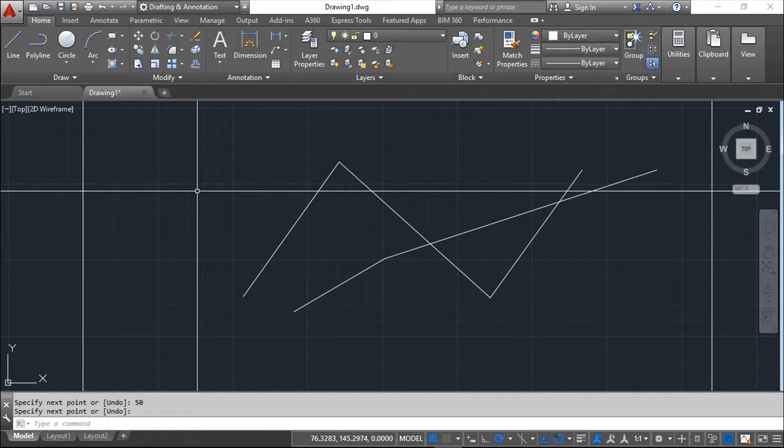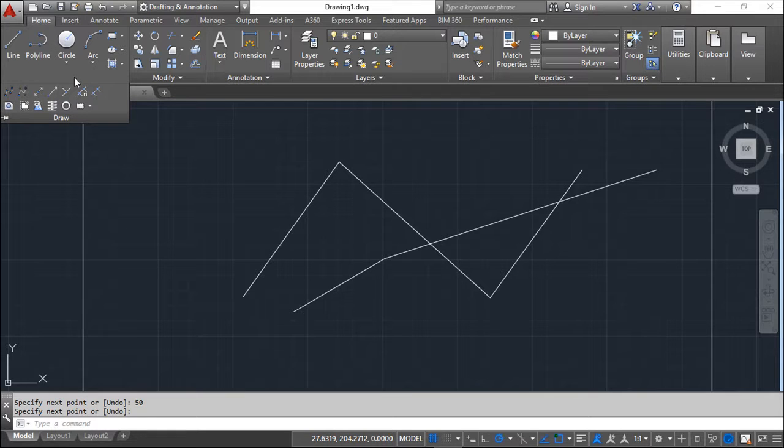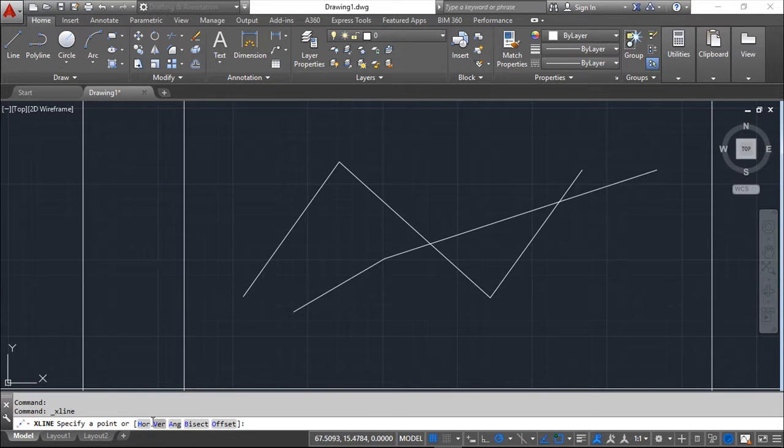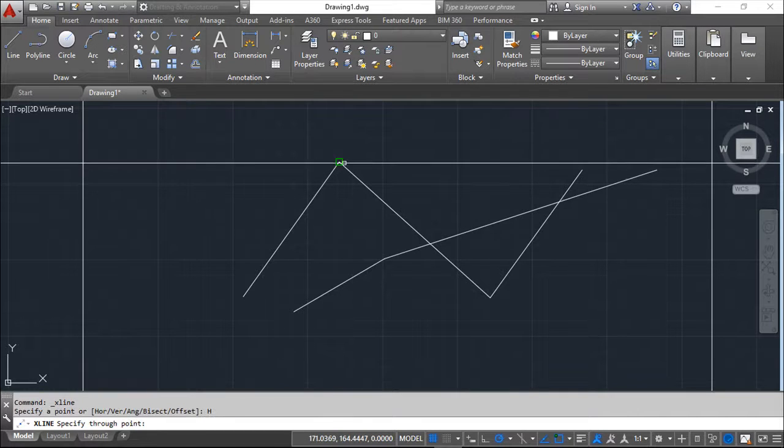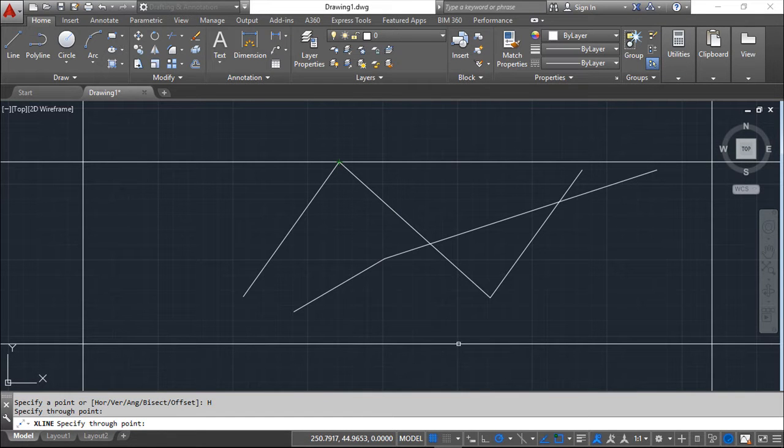Another thing I would like to show you today, which complements this information, and is another tool for your drawings, are the construction lines. The construction line can be found in this Draw menu. I have this functionality here, construction line, and now you have a couple of options in this toolbar and the command line, which are very easy to understand. First, horizontal: just click a point, okay, and it will make a horizontal line. And these construction lines have the particularity of being infinite.